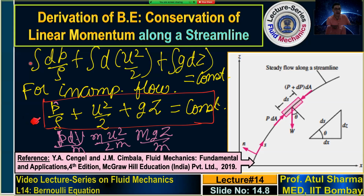You can express P by rho as the product of pressure into volume divided by mass, because mass divided by volume gives you the density in the denominator. So this P by rho corresponds to flow work, flow energy, and this is kinetic energy, and this is potential energy. However, each of these terms is energy per unit mass.